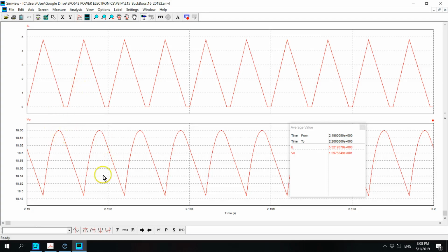and therefore when we operate under this discontinuous current mode, if you look at the output current, you cannot apply that equation anymore. The output voltage equation, which is equal to V in multiplied by D divided by 1 minus D. The output voltage is always greater than the voltage found by that equation, V in multiplied by D divided by 1 minus D.